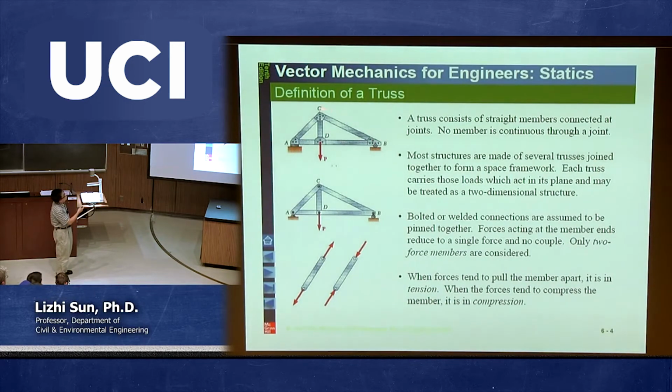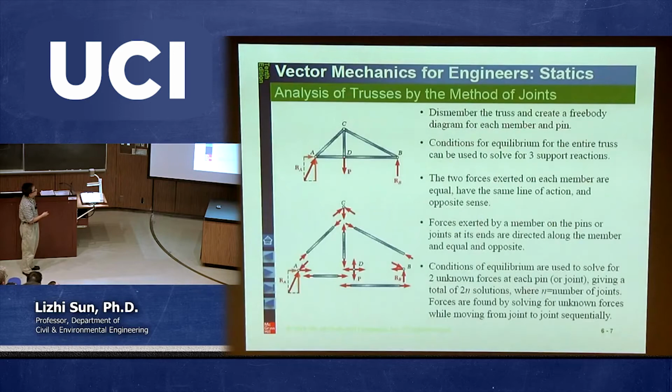And that's very easy to do because we just identify the whole truss as a rigid body. At point A is a pin end, so we give 2 reactions. At point B is a rocker, or roller, so you give another reaction, and then all together form the free body diagram.